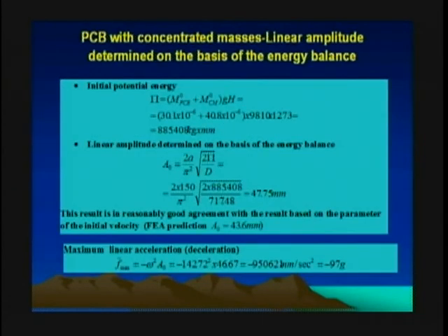Also, I used other approaches that have to do, always useful, with the energy balances, because in this situation, we certainly know with high certainty the initial potential energy, and then we want to understand how this initial potential energy manifests into other energies itself, and then how we calculate that, and we obtained a very good agreement. When I based that on the energy balance, I obtained the amplitude of the linear vibrations of 47.75 millimeters,